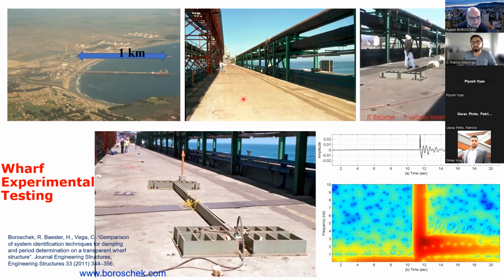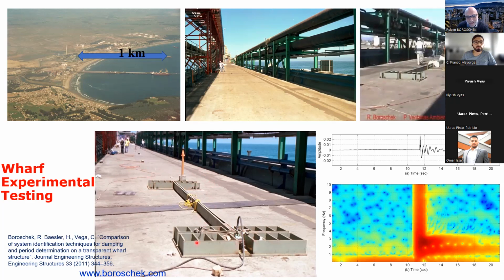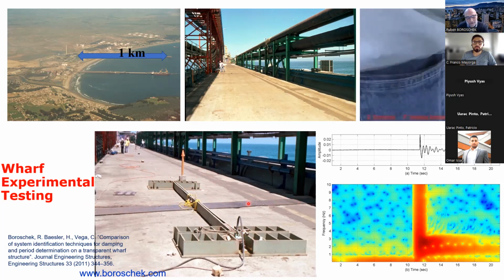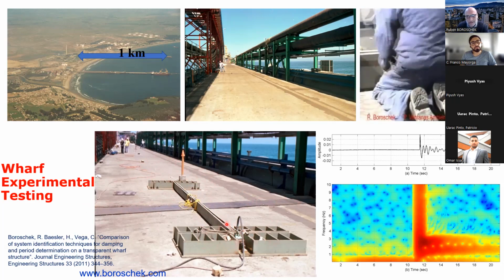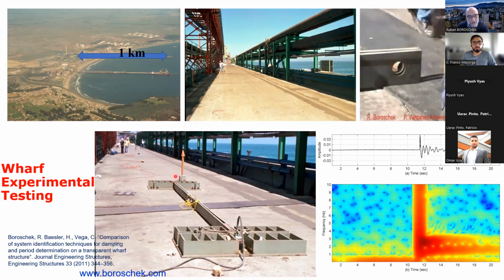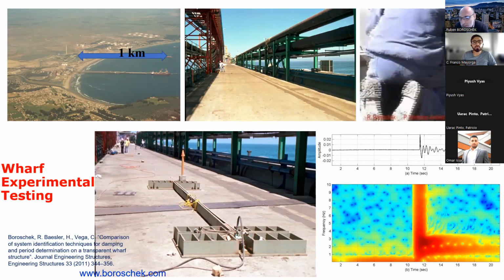So I grabbed this graduate student, last name is Vega, and another professor, Baxler, and we designed a pulling system. We just anchor the system here, anchor the system here. This is a construction gap or just a dilatation gap for wave motion and construction and temperature things. So we put a 100-ton jack here. We pull the system and we put some, let's say, fuse system here, and pull the whole kilometer structure and abruptly release it and get the response of the structure.